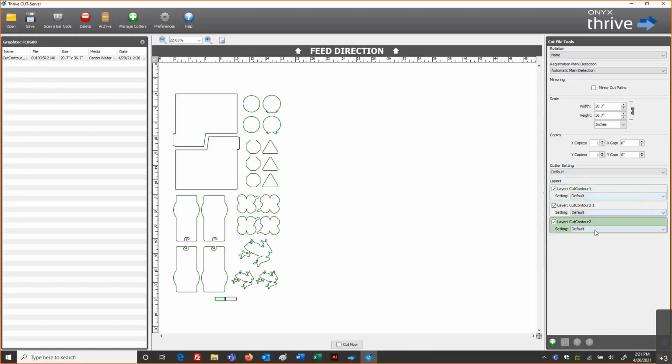This information's coming up in that display. Now, if I hover over those areas, we can see where those cut paths are. They illuminate in that green color. If I click on the objects, I can see them represented as this purple color. So again, we can always see what that cut path information is going to be.